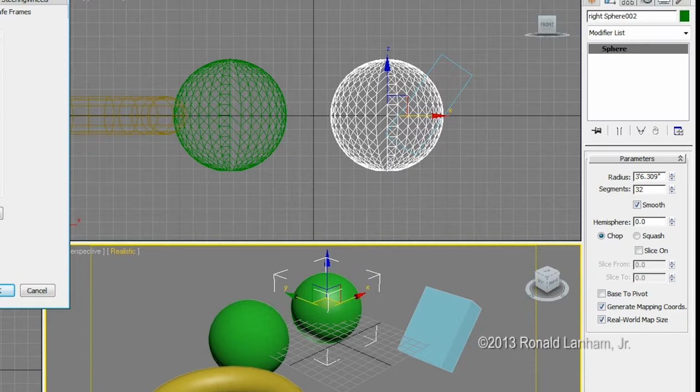They should be on by default, but they are. So you need to come up to the viewport configuration and set your save frames to Action Save and Title Save. And then when I apply that, if you watch down here, okay, now we have different views. Now I need to turn off user save. Okay, so